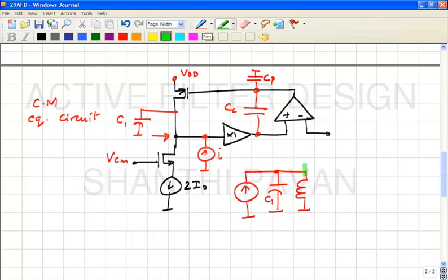So there must be a resistor in parallel with the inductor. This is what must be happening. Okay, we try to understand why, how this happens. Please note that it's actually quite straightforward to go and sit and write the maths and get the expression. What I am trying to do is to derive intuition for why this equivalent circuit makes sense, and why CC can be interpreted as introducing a parallel net resistive loss in this second order network.